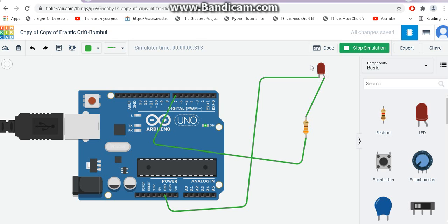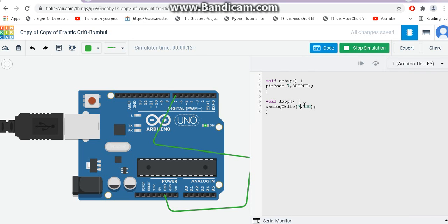So you decrease the voltage using those analog values, and the LED's brightness goes down in your real Arduino. And when you reach a particular analog value, the LED is not even switched on. So you say, with this voltage we cannot even switch on the LED. Above this particular voltage, we can slowly increase the brightness up to the maximum at 5 volts. Guys, you get this. So you can find your own value: what is the exact analog value where the LED goes off, and you can let me know in the comments. For the moment I am just taking 100 and seeing what the voltage value is.